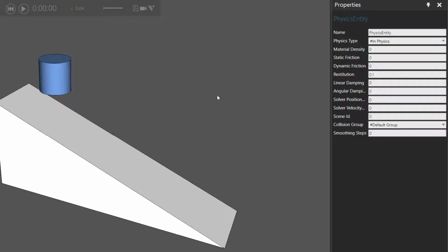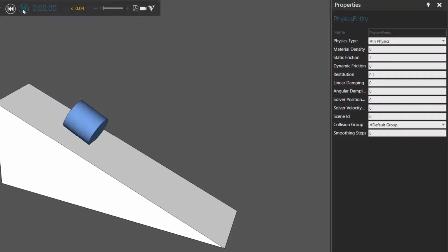Let's now reset. And what you need to get used to is tweaking these values in steps. So usually I do the 0 test second after doing a default test, and then I test, okay, what happens if static friction is 1 and dynamic friction is 0? So let's now test. Oh, we get that. So when the cylinder collided with the ramp, it kind of jerked or snapped from that friction and fell over, and that's what's keeping it right here.